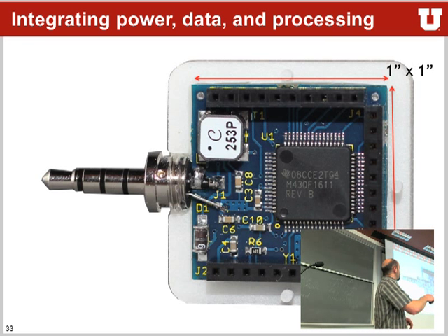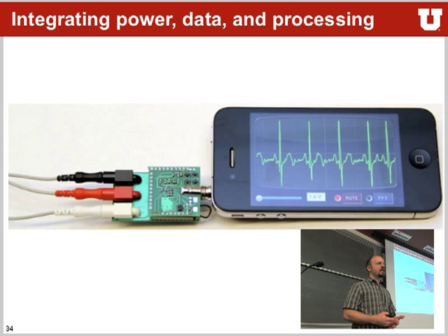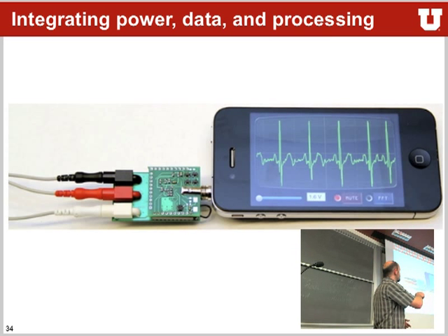We have some circuitry on there, but really not that much. And most of this part over here is for power harvesting from your headset port. So you have a microcontroller, you have something that generates your power, and then you have a headset port, and you use that headset port for communication, which basically makes an embedded system, right? You have an EKG system that was plugged on top of it, that was monitoring and taking the EKG leads and your heart rhythm.